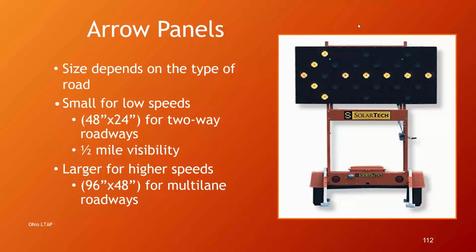Like I said, it would draw attention away from the flagger, and also an arrow would tell the motorist that you can go around blindly without even thinking. You can't do that in a flagging operation because there's traffic coming the other way. That's how you'd create a head-on collision.